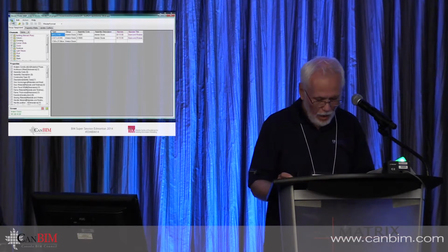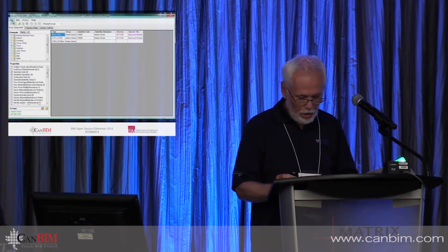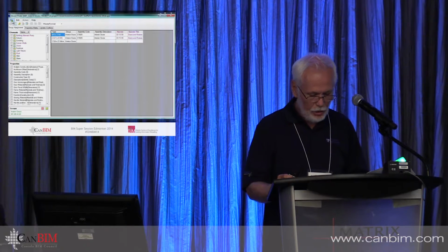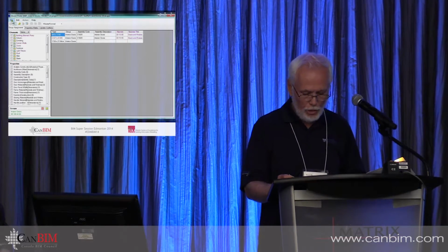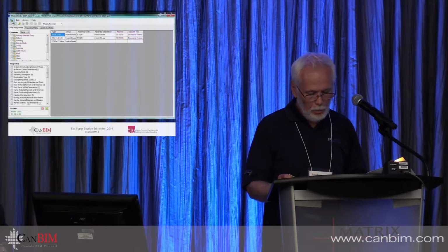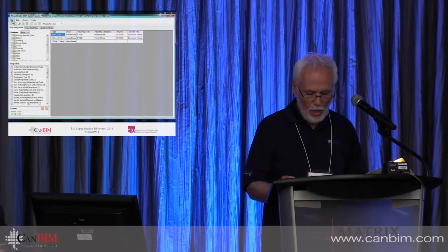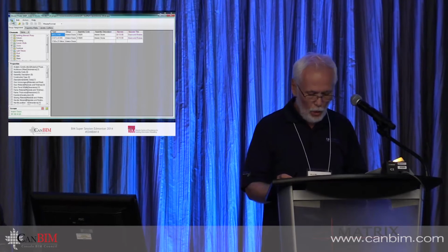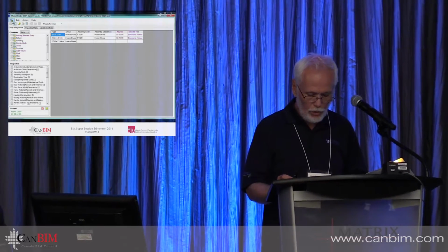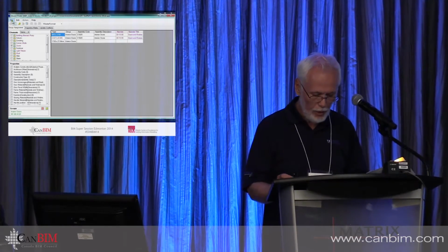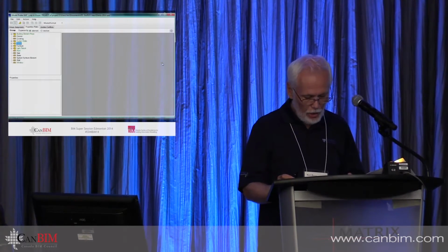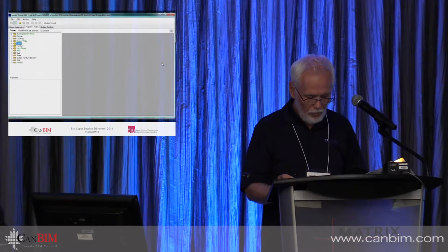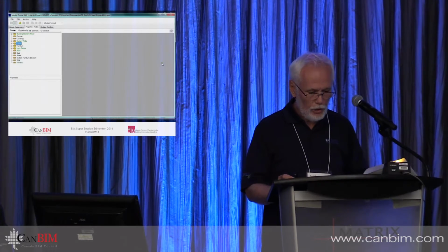Sorry about that. Sometimes a property in the BIM model has not been set or has been set incorrectly. The spec writer can enter values for these properties and return them to the designer. To do this, he exports the changes from Spec Edit to a file, passes the file to the designer, who can use the Spec Edit plugin to show those changes in the modeling program, either Revit or AutoCAD. He can review the entries and accept the ones he agrees with. This updates the model so it is in sync with the specs.